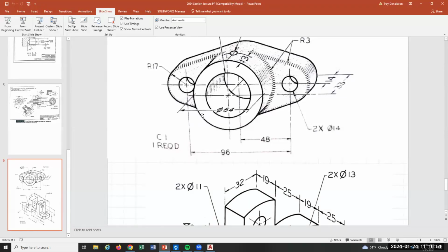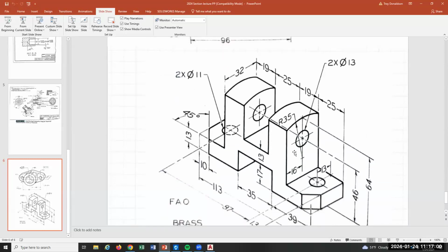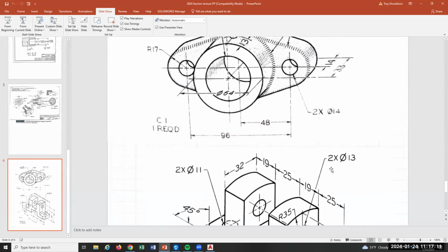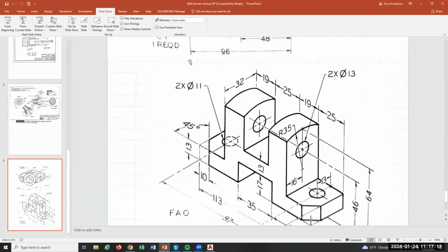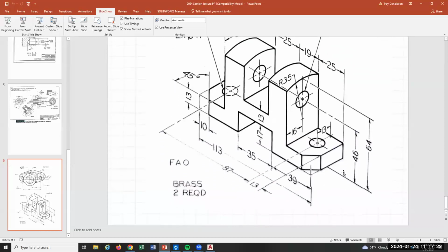So you're going to draw the front view, put the cutting plane in, and then draw the section. This one, I believe you're doing the top view, and then you're doing a full section, you're going to cut through it, and that'll become the front view. These don't have really complicated inside geometry. That's all right, it's still good practice. It's going to give you a lot of opportunity to dimension things that were hidden lines that will go away.